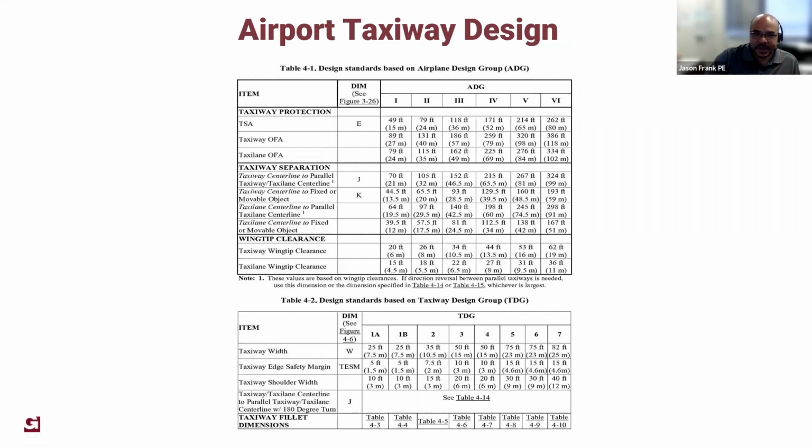When you're designing taxiways, a lot of the work is just to consider yourself in a car, or in an aircraft cockpit, over centerline. The pilot follows that centerline because he's in the cockpit, so it just makes sense. It's always cockpit over centerline. You want to make sure that he or she follows the route that you give through the airport.